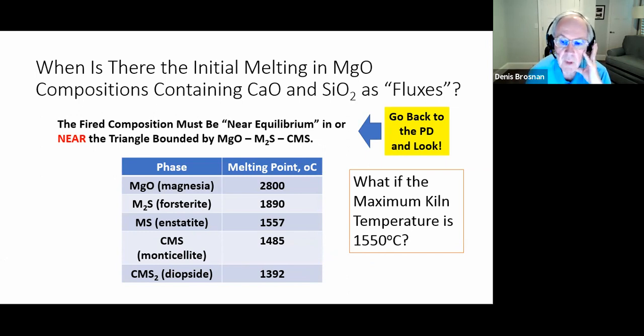So I know that you can get magnesite or magnesium oxide that's natural, that contains a lot of iron or other impurities, but we're going to assume that we're making this object out of synthetic magnesia that was made from brine, calcined, turned into caustic magnesium oxide, briquetted, fired to very high temperatures to form high purity magnesia aggregate.